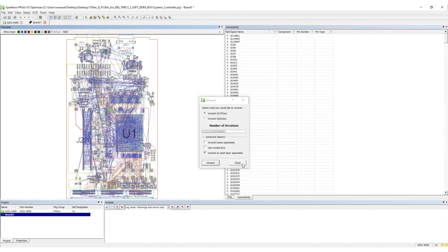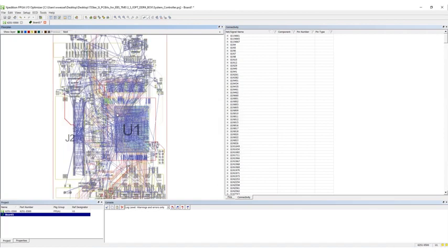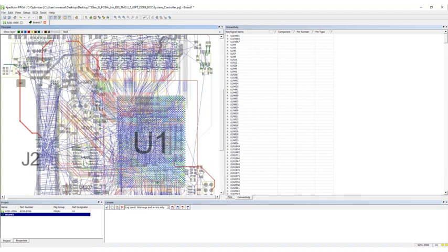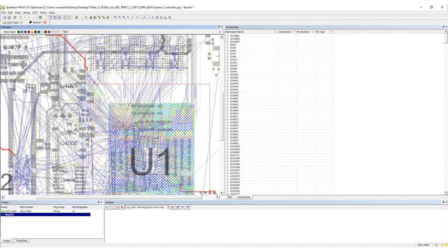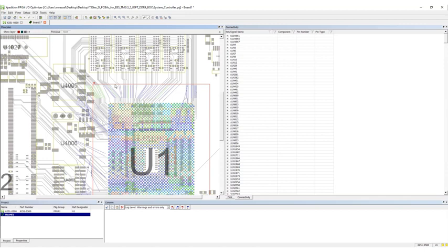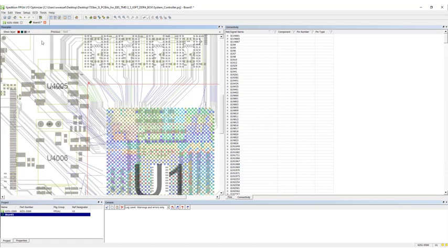As we see, the clear advantage of this second step is a much faster routing time. The support of optimization between trace ends guarantees layer reduction and minimum net length. All this reduces signal integrity issues, which makes our SI-PI engineer Rory very happy.